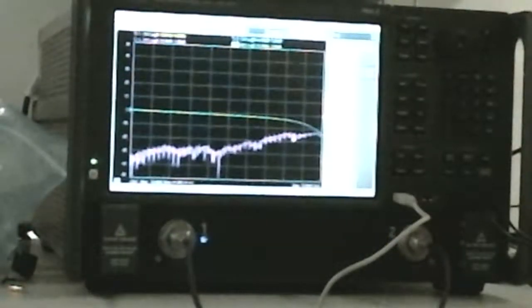And now I've got the gain of this cable. I can see that the reason this cable is not very good is that probably around 10 gigahertz is where this cable is rated. Anything beyond that, and I'm really pushing the performance of the cable. If I wanted to add a marker here, I can do that very quickly with right-clicking, and I can verify that at about 10 gigahertz we start seeing some of those issues.